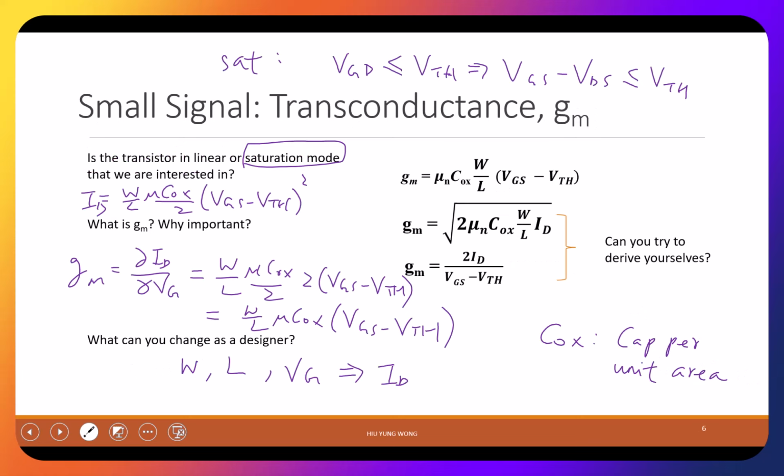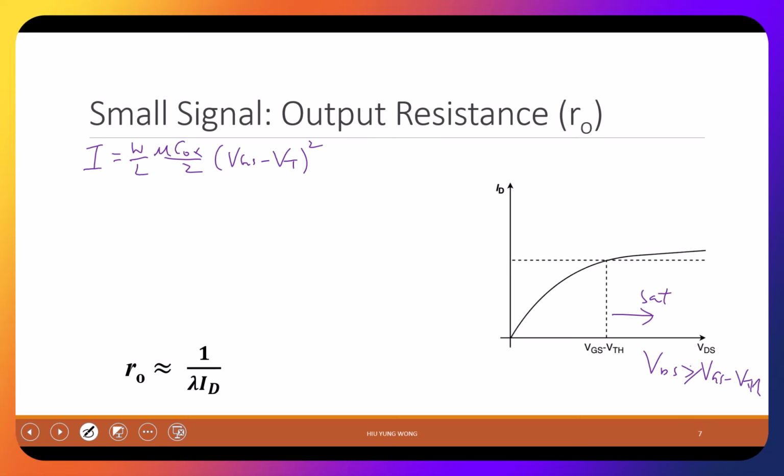I really forgot. Did we discuss this actually? I think we discussed this, sorry. But I did not give you the formula for the channel length modulation. It does depend on VDS. So the empirical way is to say this current goes up with 1 plus lambda times VDS. This lambda is very small, right? For example, the lambda can be 0.01 per volt.